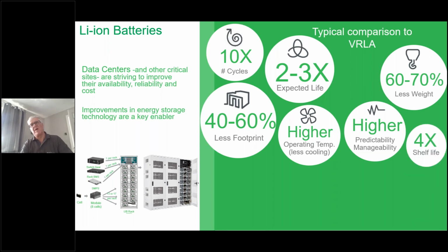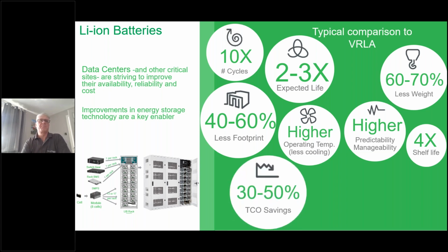4 times the shelf life. Unlike a VRLA, which you need to recharge every 6 months if it's in storage, your lithium-ion battery could go into storage and sit there, provided it's within the environment suggested by the manufacturer. It will sit there for a certain amount of time. You won't need to pull it out and think about a way of recovering or recharging the battery.